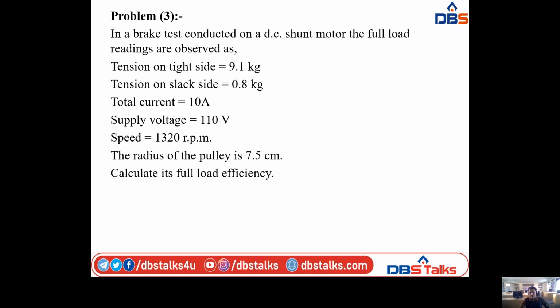And motor output power, you know the formula to calculate the motor output power, that is equal to input minus total losses. So here the input power is 8705.5 watts minus total loss, which is nothing but the copper loss plus stray losses. So here the copper loss for the motor is 647.27. Copper loss is nothing but the combination of field copper loss and armature copper loss.